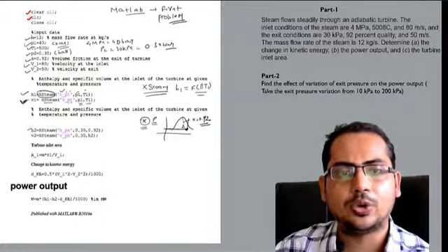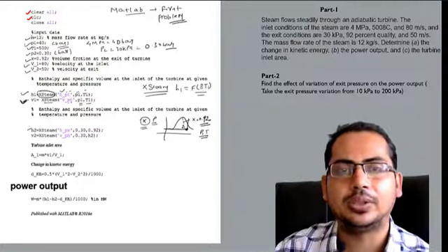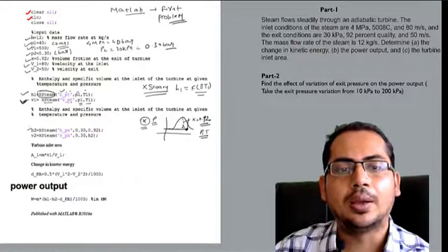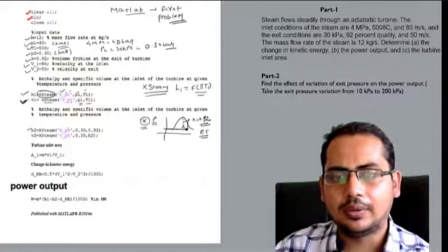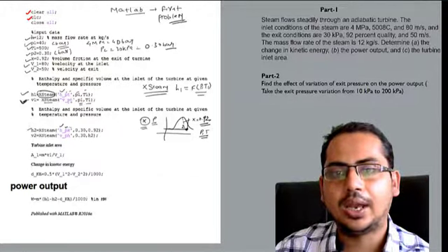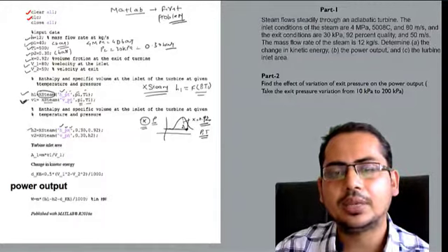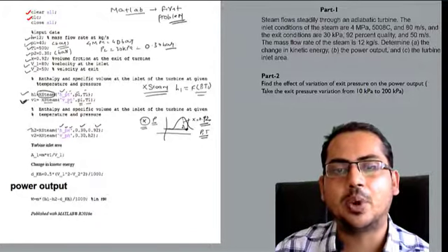In the saturated zone, from pressure and temperature you cannot fix the state of the system. You need to know either pressure and dryness fraction, or pressure and specific volume. From that you can fix the state of the system. So here, to calculate the enthalpy H, pressure and dryness fraction are the inputs. The pressure value is 0.3 bar and the dryness fraction value is 0.92.